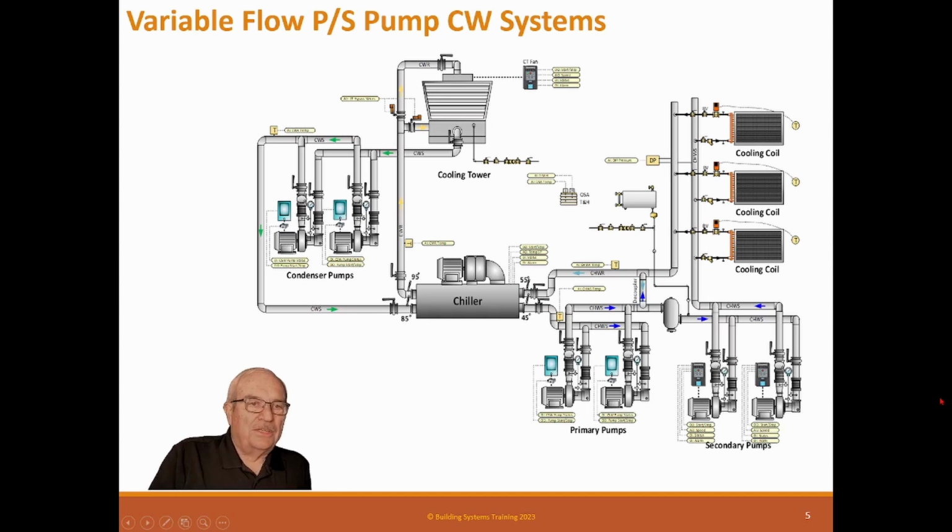Well, it turns out, the decoupler should be full pipe size. It should not be a reduced decoupler, which you see sometimes, which can be okay. But what happens is in your drawings, it's a diagram drawing, and you see this decoupler on the diagram, which looks real simple. It looks like it's in the right place and everything. But if you actually get out to the field and you look at this pipe, boy, this pipe is like spaghetti out there. It doesn't look anything like it does in this diagram. That's where we get into trouble. And sometimes the decoupler is a vertical pipe, not a nice horizontal pipe like on the drawings. So basically, we should pay attention to that.